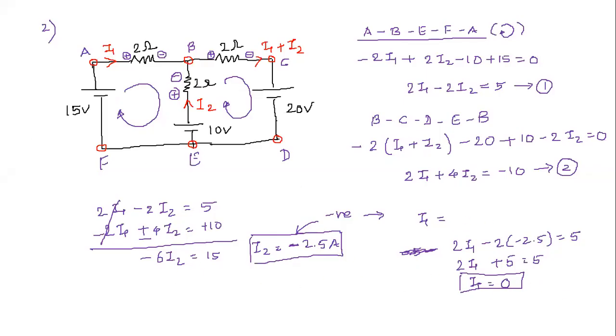But the point I want to make here is, when you look at the circuit, you won't always get at first instance what is happening inside the circuit. So we need to solve a circuit, and that is why we are using these methods, right? Sometimes you will be dealing with tricky problems. So this is a redundant branch, as if it is in the circuit, but it is not taking any current.